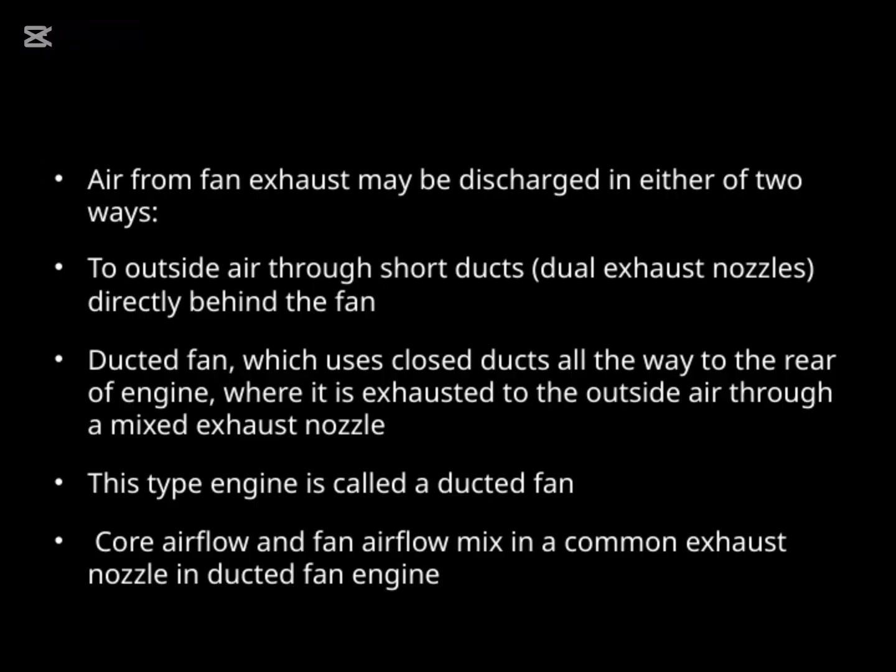The second method involves a ducted fan, where all the airflow is channeled through closed ducts that run all the way to the rear of the engine. At the back, the airflow is expelled through what's called a mixed exhaust nozzle. This configuration, where the airflow is fully ducted, is what we call a ducted fan engine.